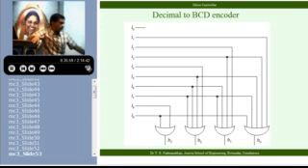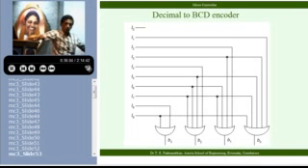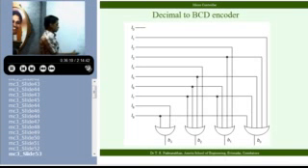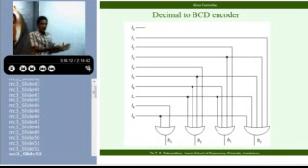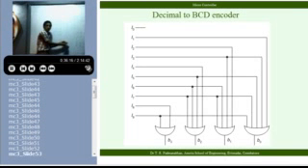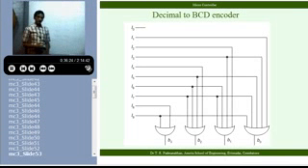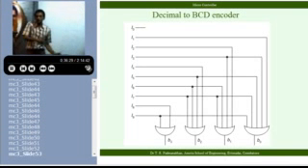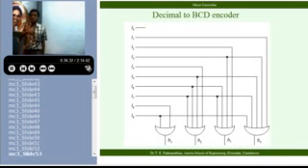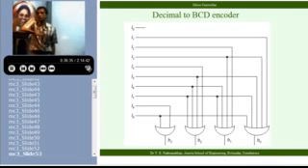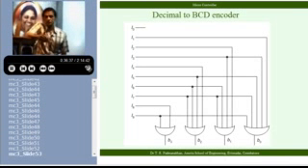At that time, the complete algebra used to be done in decimal form. The number was represented, individual digits were represented in this form. A 3-digit number used to be represented like this. When you do an addition, you add these two, and see whether you have got a carry, a decimal carry. There is no binary carry here. You see whether you got a decimal carry, take it and carry over here. See whether you got a decimal carry over here. Like that, the circuit was worked out and everything was implemented in that manner. That was a very widely prevalent set of applications with BCD.